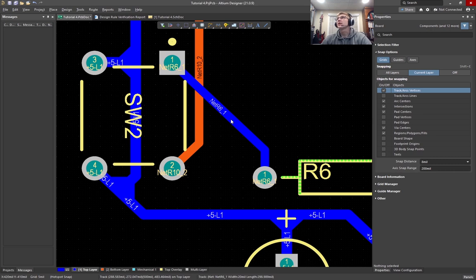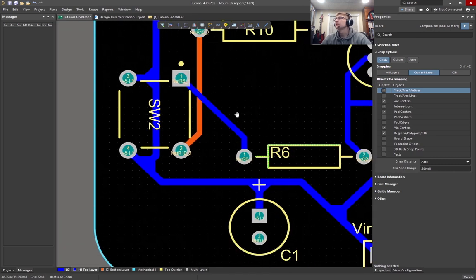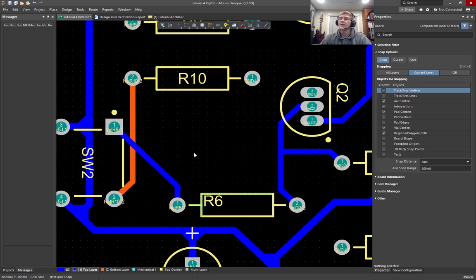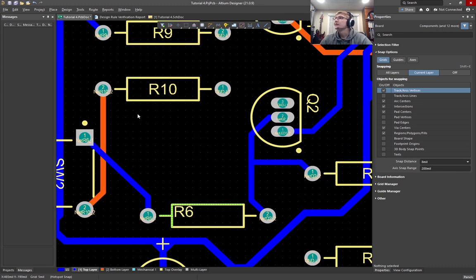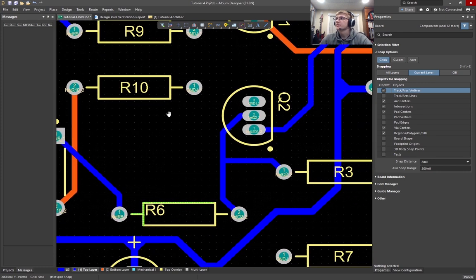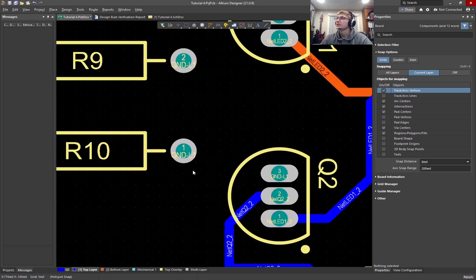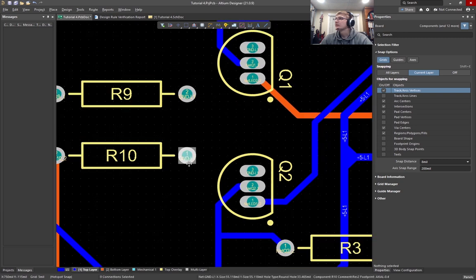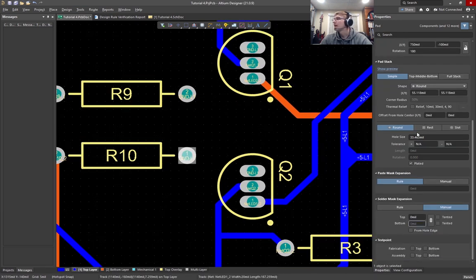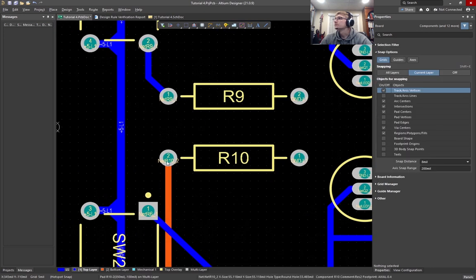Another one that you're going to see super often is something called the solder mask expansion rule. Basically, when they go to coat a circuit board with the color that you see on top, either green or actually JLC has a couple different options, they're going to cure it, usually with UV light or something similar, and then that's going to harden on top of the board. And when it does that, it's going to change size a little bit. That's called the solder mask expansion. So you need to have some tolerance room for the solder mask to expand, and that's something that you actually specify in your rules. I have done it already for some parts.